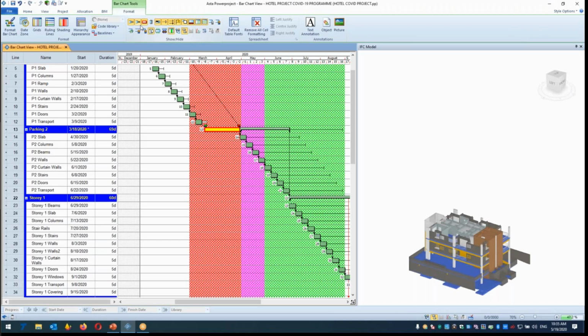What I suggest is splitting your project into two parts, before COVID and after COVID, because this kind of time extension, let's say 6 months, will probably cause all your remaining activities to become critical. Generally, if we have a 5 days delay in one activity, or 2 days delay in activities, we can make a critical path analysis. But if we are speaking about 1 month, 2 months, 3 months delay, it will probably cause 90%, 80% of your remaining activities to be critical.